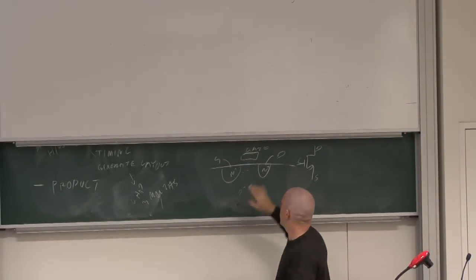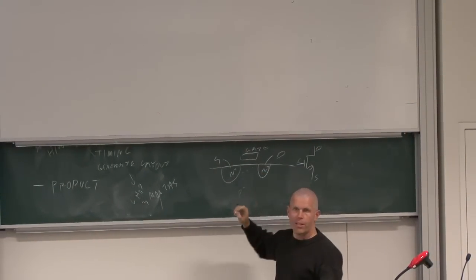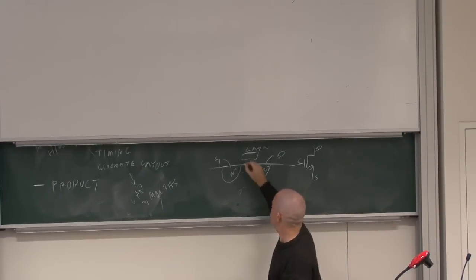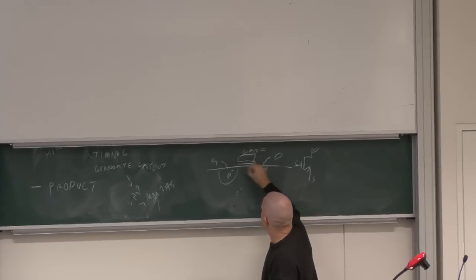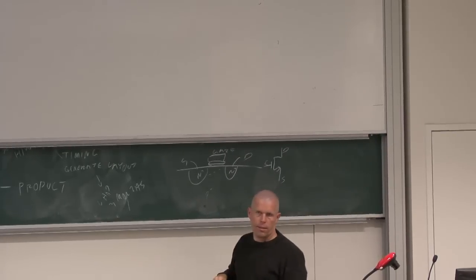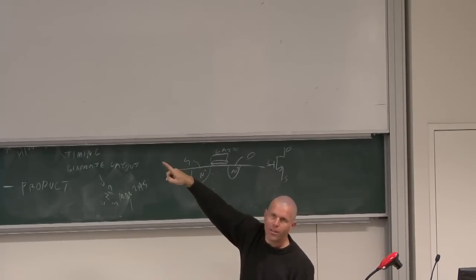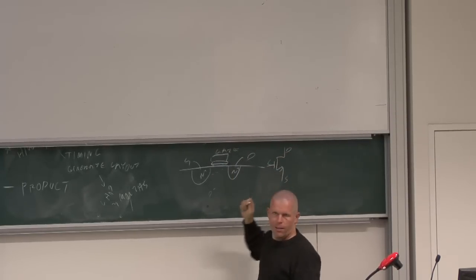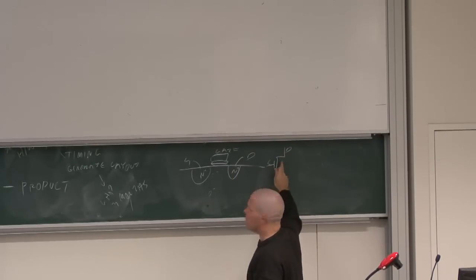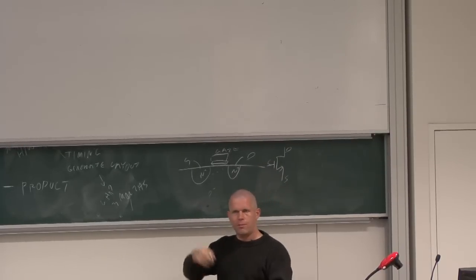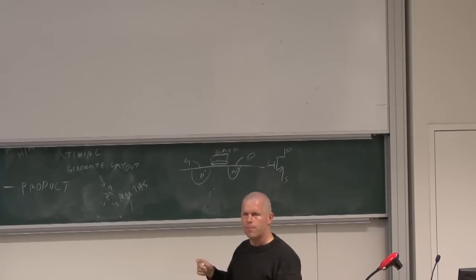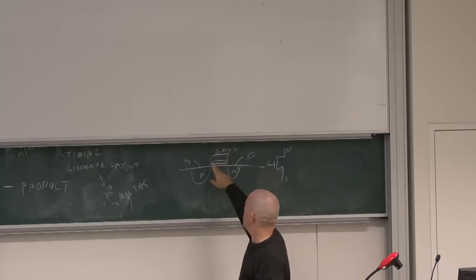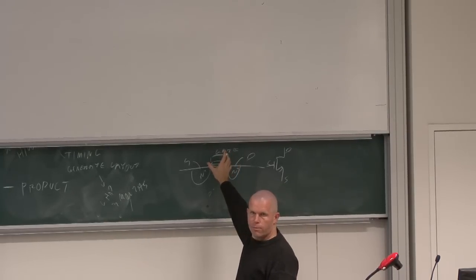Typically the minimum feature size you can produce is this dimension here. So when I'm talking about 40 nanometer, that means the length of the gate, the smallest I can build, is 40 nanometers. I can build them longer, and if you've done any work with FETs, you'll have played with the width and length parameters. Basically this is the smallest thing we build.